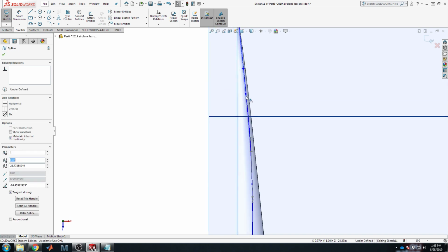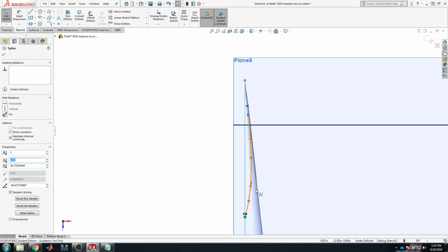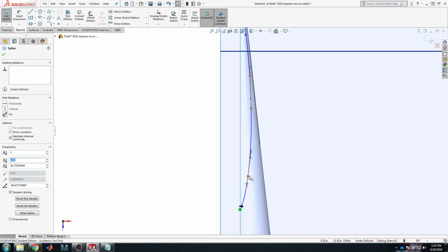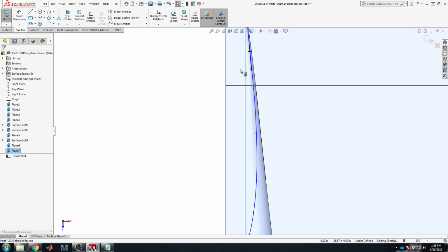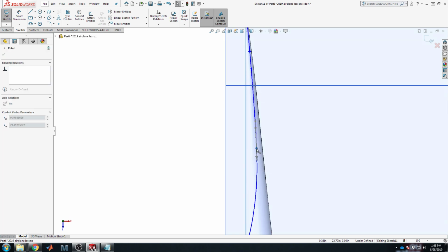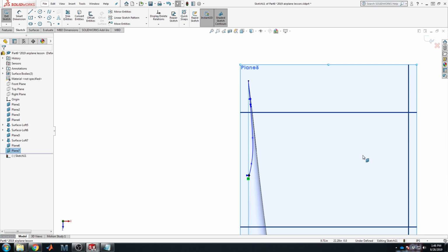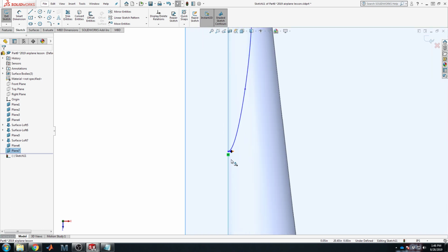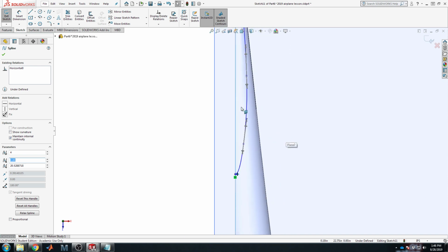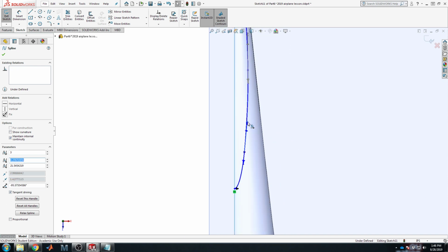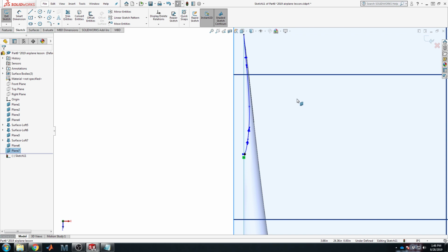And really, unless you're going to be building the tails into your molds, which we're going to have a lot more conversation about as you get towards the molding portion of these assignments, you probably don't need to worry too much about making these exact. In fact, in this actual DBF competition year, they ended up using flat plate, just built up balsa wood tails because they're the lightest and honestly the quickest to make too. Didn't have to make molds, didn't have to mess with all those other time sinks.